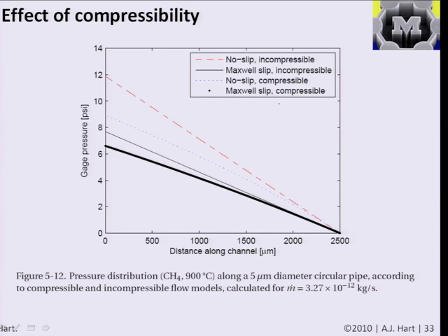It can be important in a number of ways, but for microfluidics, if you have such a small device, it's very difficult to measure flow. It's typically done where you apply a certain pressure to a device, and then you expect a certain flow to go through the device. And because of these big differences, the amount of flow that's actually going through can be different, so that can make a big difference in the practical operation of the device.